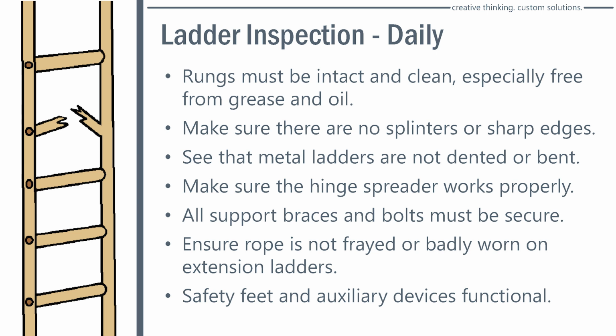So what do we inspect for? Things like, are the rungs intact, clean, free from grease and oil? No splinters, sharp edges. How about dents, cracks, bent pieces? The hinge spreader works properly. Support braces and bolts are secured. Ensure the rope is not frayed or badly worn on extension ladders. The safety feet and auxiliary device functions.